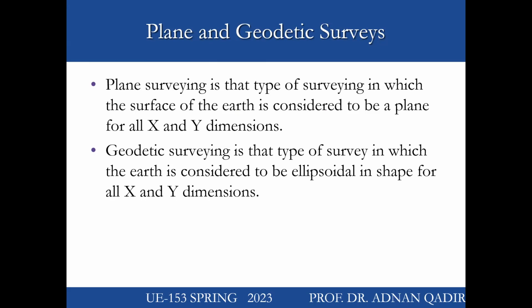Sometimes we need to have a geodetic survey, just like for aerial photographs. But for a small scale, say for instance, if I have to lay out a building of around 1,000 square meters, I may not need the curvature of the ground. But if I'm talking about building a coastal harbor, or an airport and all those things, a larger project, then we cannot ignore the curvature. So depending upon the purpose of the survey, we can perform plane surveying, or we need to perform geodetic survey, or we need to take the curvature into account while measuring.